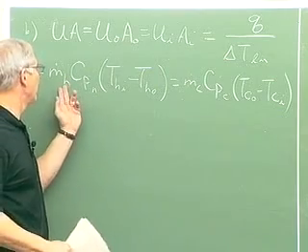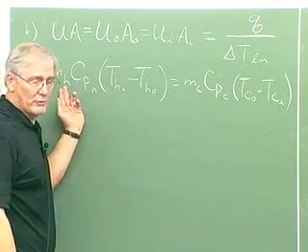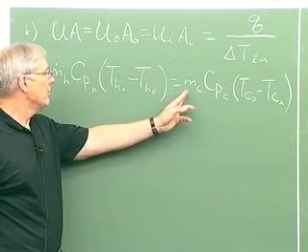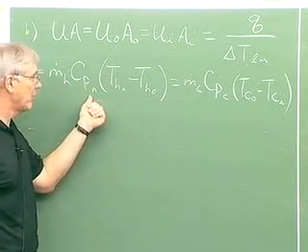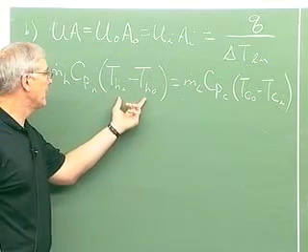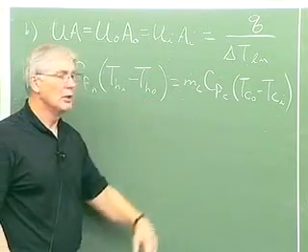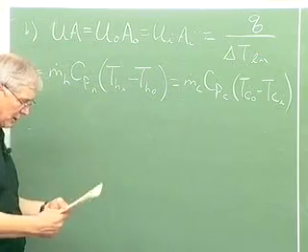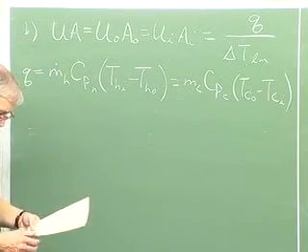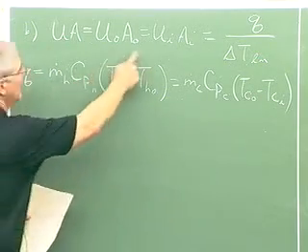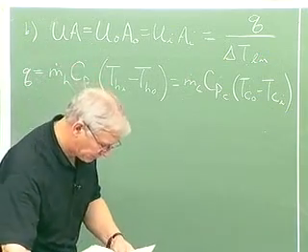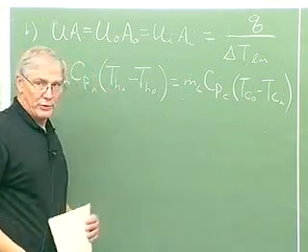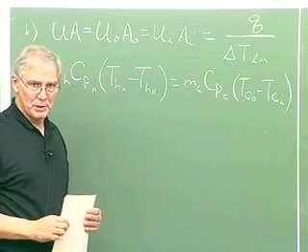In lab, we measure the hot flow mass flow rate and the cold flow mass flow rate. We can look up the specific heats, and we also have measured the hot and cold flow temperatures. So we can get Q, and then once we have that, we can plug that into this expression and we can get UA. So that's how we get UA experimentally.